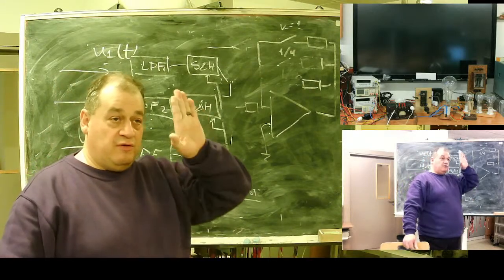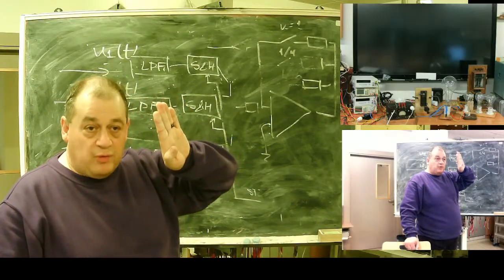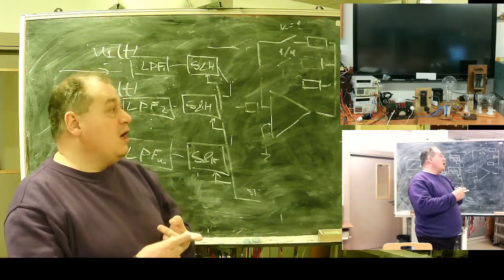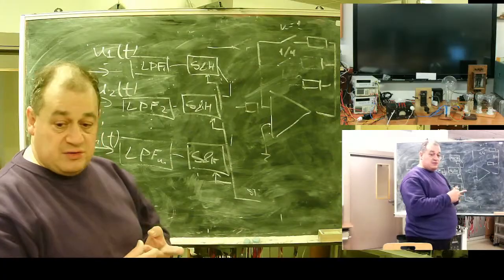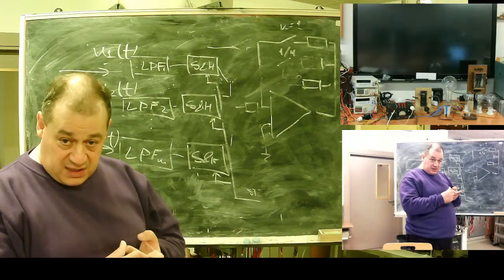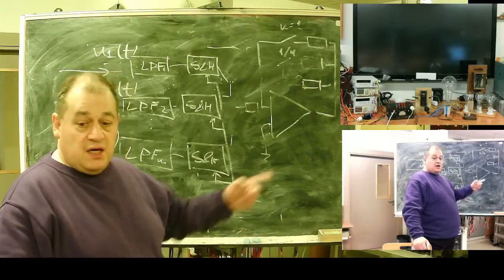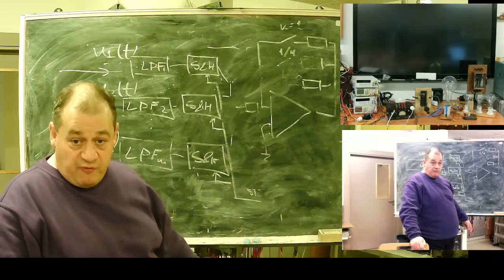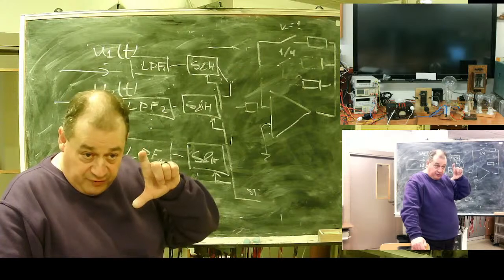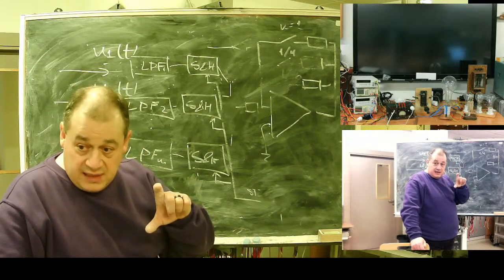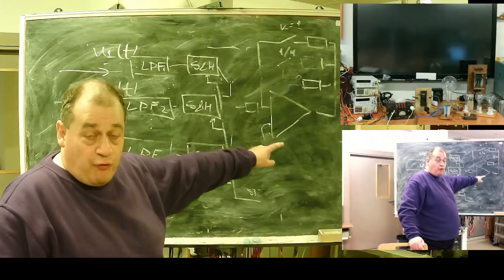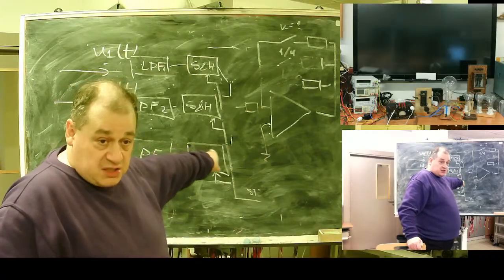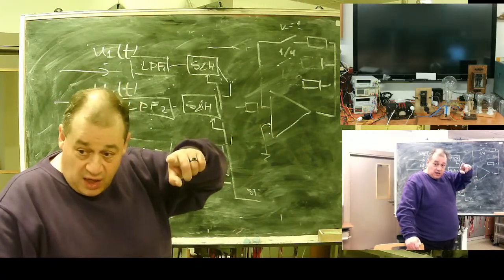First, time to do sample. Command number 1, send freeze to sample and hold. Command number 2, select channel 1 from multiplexer. Command number 3, set PGA to 1/16. Command number 4, perform measurement with ADC, rough. Establish best gain, send gain command, perform precise measurement. Set gain to 1/16, switch multiplexer to channel 1, perform the same for channel 1, and so on.